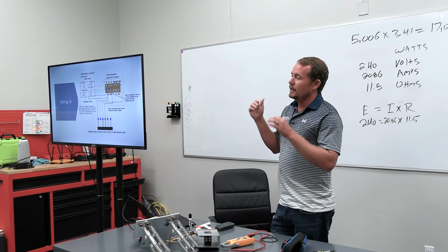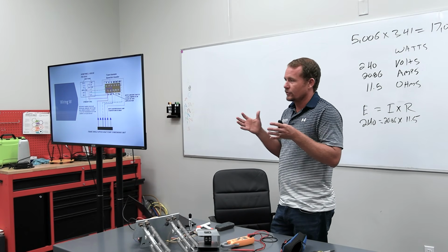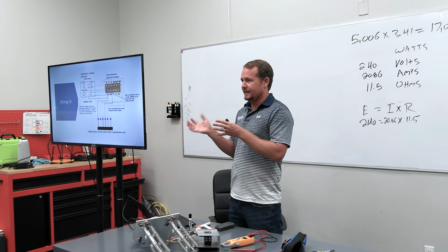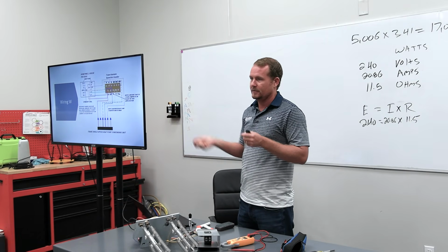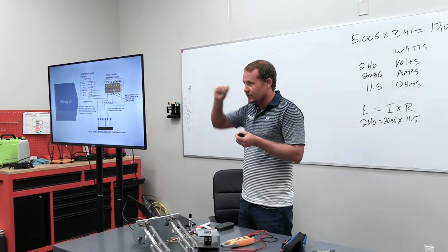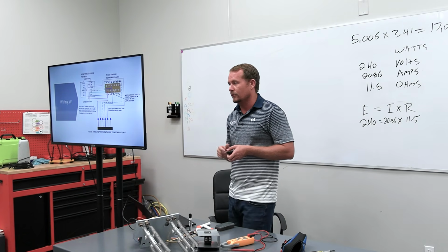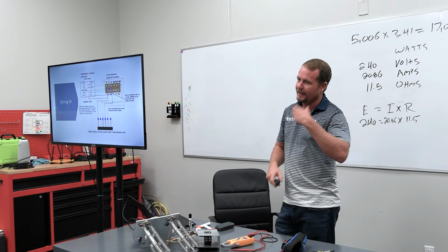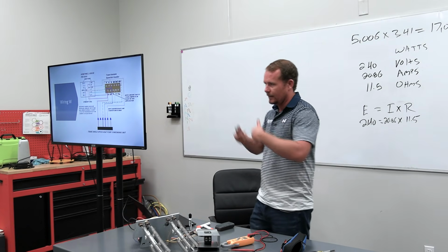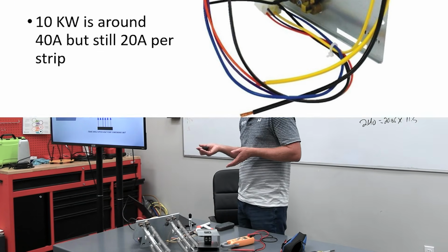Yeah, so in those types of thermostats, you didn't have internal logic. So the only way you could tell it what kind of system it was was by putting jumpers in place. And you'll still see some of these. You'll actually have physical jumpers in place. And so you had to jumper Y1 to W1. Nowadays, you tell the thermostat that it's a heat pump, and it automatically does that. It automatically just energizes Y in both heat and cool.